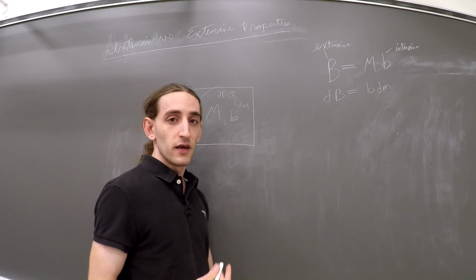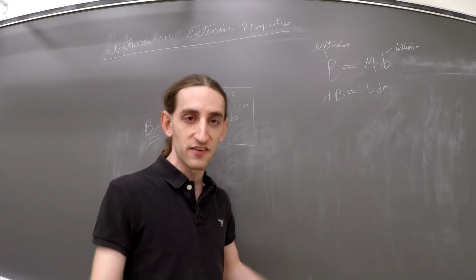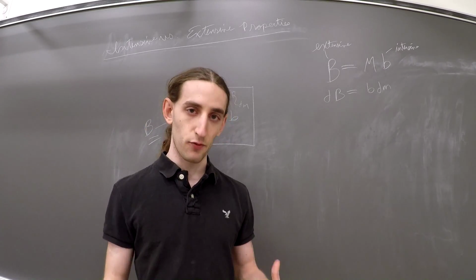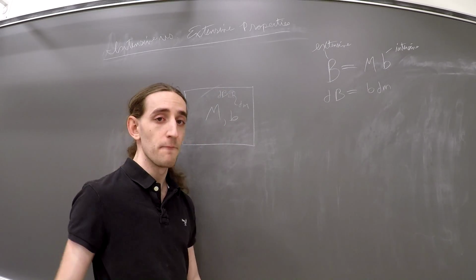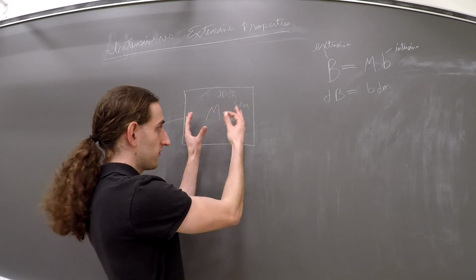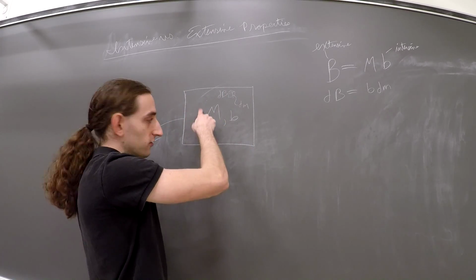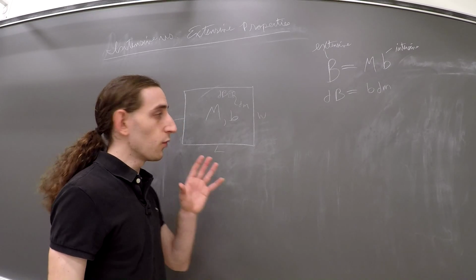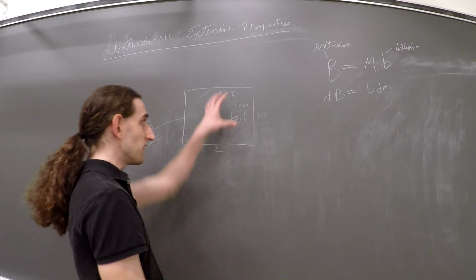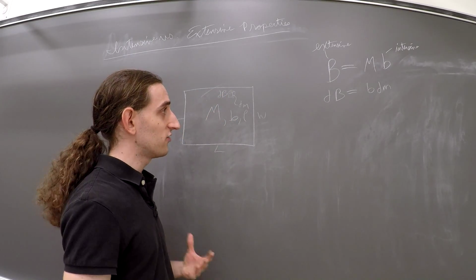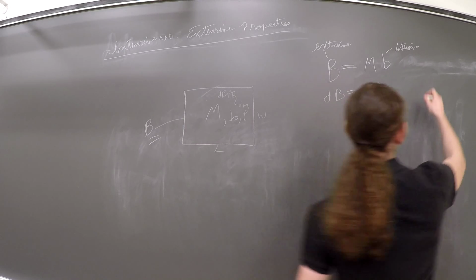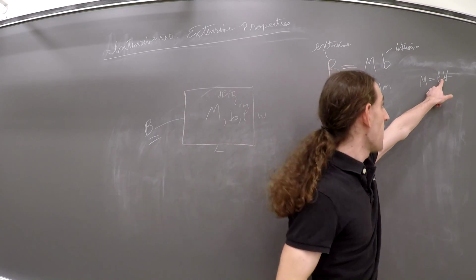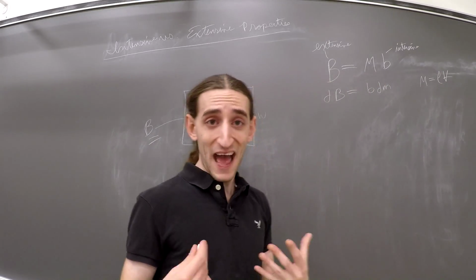What's really good about this framework of intensive versus extensive properties is that we can break this mass down into something that allows us to perform the calculation very easily. It's not as easy from a geometric standpoint to measure the mass in our system. It's harder to figure out the total mass than the volume, because we could just take the length, width, and height, multiply them, and figure out our volume. But with intensive properties, we can say there's a density throughout this that is uniform and constant, and that allows us to express this dm, or m, as rho times the volume of the system. Because this is mass per volume times volume, that's going to give us our mass back.